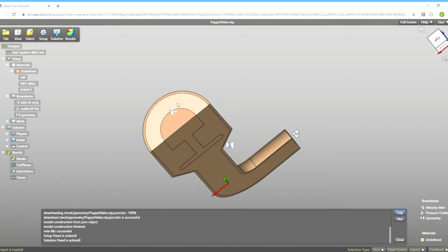Remove a boundary condition from here, or we can modify it by editing it again. All actions can be reached from context menu, or double-click Tree Node for opening edit. Now we need to set material on part rather than on surface. So we could switch selection type on ribbon, toggle part selection type. We also can switch type by this menu button. Double-click is another way to toggle your selection type.